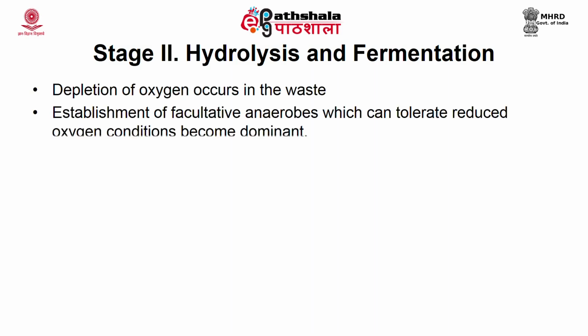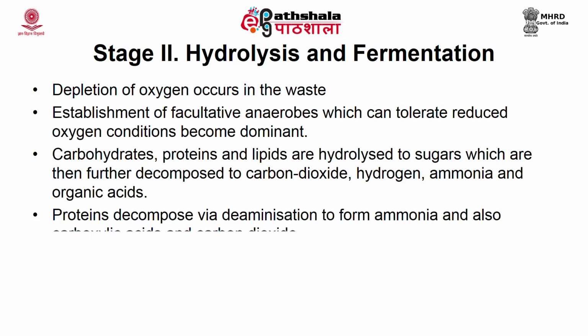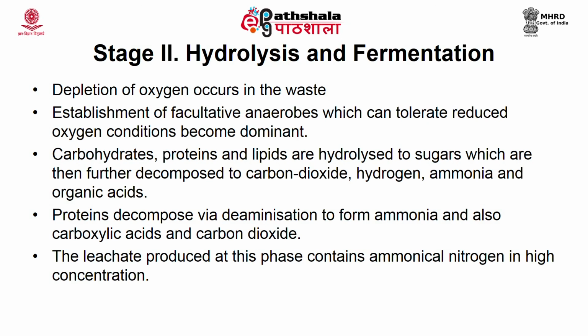Now, stage 1 will end when there is depletion of oxygen, when the oxygen is completely taken up by the microorganisms. Once there is depletion of oxygen, the aerobic microorganisms will die and be replaced by your anaerobic organisms, and your anaerobic process will start. Mostly you see facultative anaerobes, facultative meaning those which can tolerate reduced oxygen levels, and they will start growing.